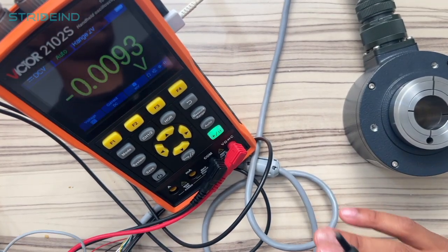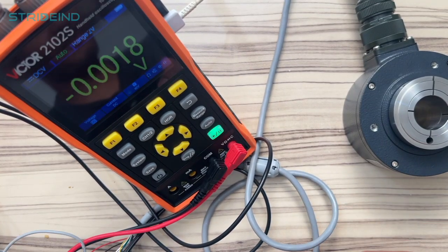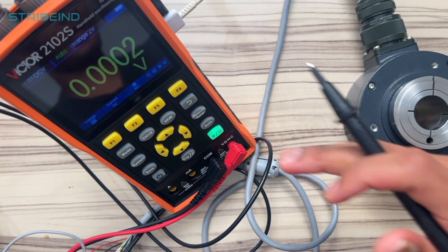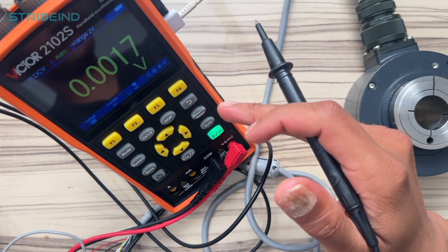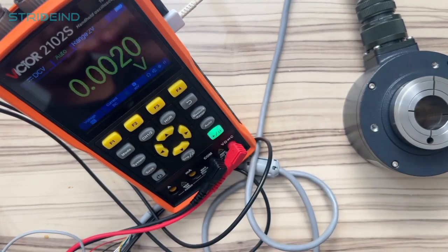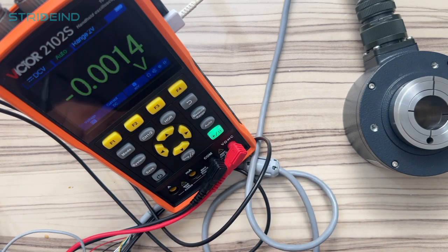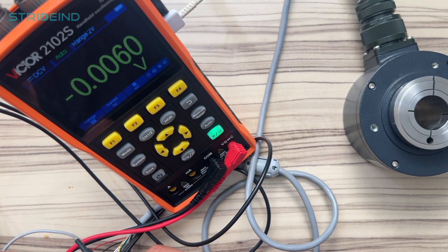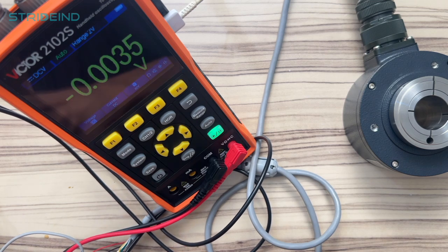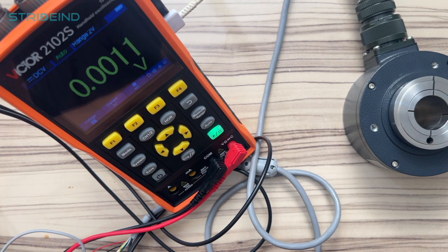As a standard troubleshooting step, first we need to verify the power is coming to the encoder. To do that, you need a multimeter with two probes. Here we have a multimeter and oscilloscope built in together, so we'll be using that one. We're going to check the supply voltage, just disconnect the fuse and check the input.